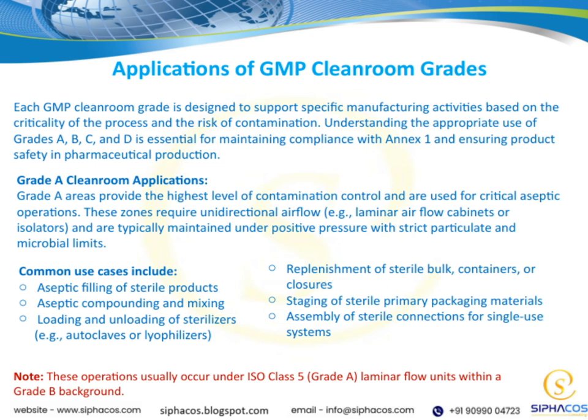Moving on to Grade A cleanroom applications, these are the highest level of contamination control. They are used for the most critical aseptic operations. These zones require unidirectional airflow, such as laminar airflow cabinets or isolators, and are usually maintained under positive pressure with strict limits on particulates and microbes.